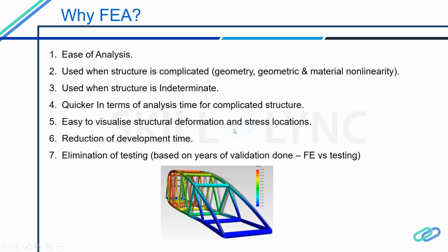And when you are performing the structural analysis of an interior monument, sometimes the customer comes back and asks where you are getting maximum deformation and which particular compartment is suffering from maximum deflection. By using tools like PATRAN, you can visualize it and give an exact answer to your customer.